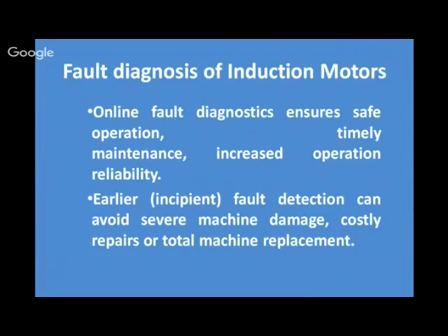Now the second part of the presentation will comprise the fault diagnosis of induction motors. Here we have the requirement of fault diagnosis at an early stage, because detection of a fault at an early stage will decrease the abrupt failure of the machine. These abrupt or catastrophic failures can damage the whole system, as well as require costly repairs and total machine replacement in some cases. So we should try to have early detection of faults in motors.